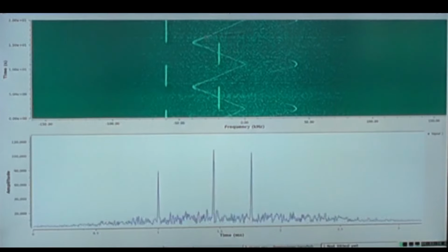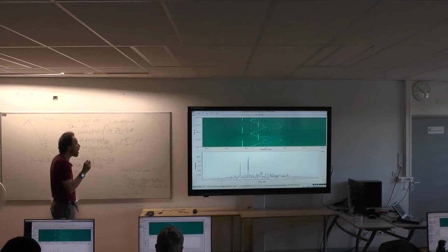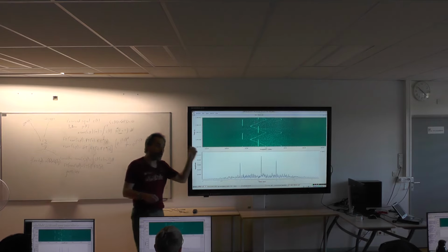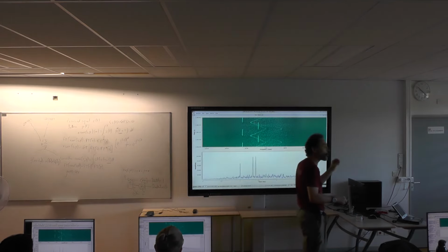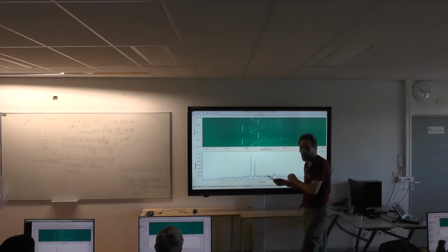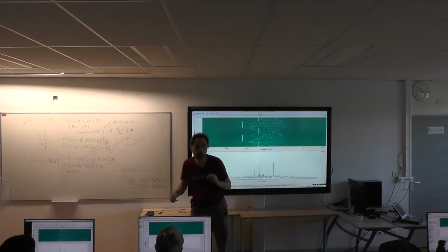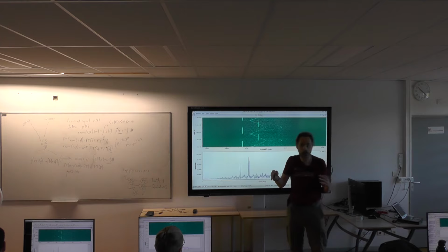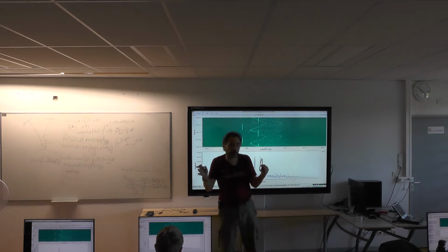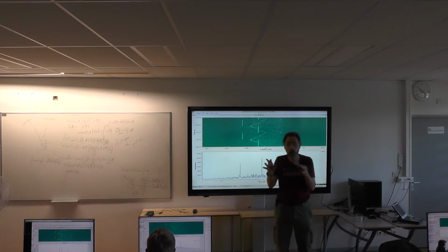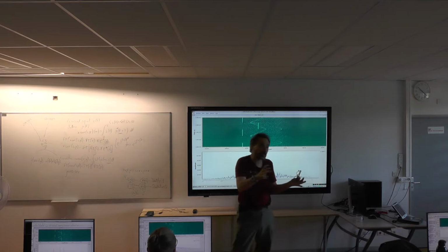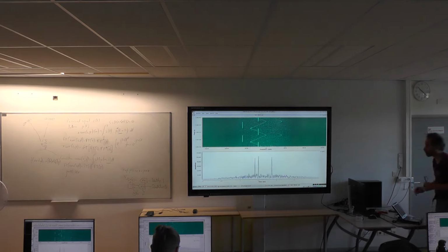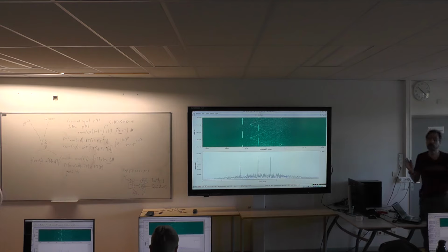Okay? So the linearity of a cross correlation means that even though our receiving antenna will get the sum voltage from all the broadcasting satellites, we still can, or if I'm talking about two-way time transfer, all the NMIs in Europe are broadcasting at the same time a two-way time transfer signal. The satellite Telstar 11N is rebroadcasting over Europe the sum of all these signals that have been incoming to the satellite, and yet you are able to identify which NMI has broadcast which signal, and you can time the time of flight from this broadcasting signal. All good so far?